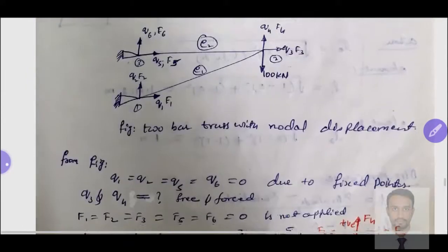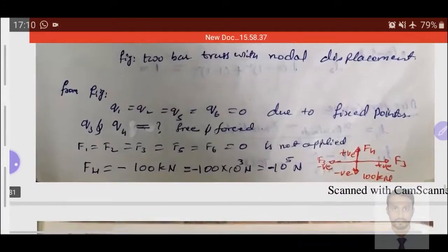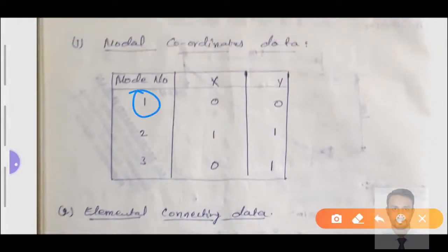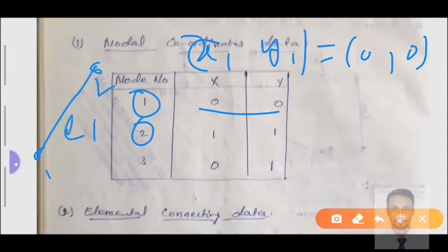Then we have these positions in the FE model similar to that. So I will consider node number 1 as the initial node and take the initial and final node values, the x1 value and the y1 value. The x1, y1 value is 0, 0 for node number 1 of element number 1, which is node number 1 and node number 2, to find out LE.